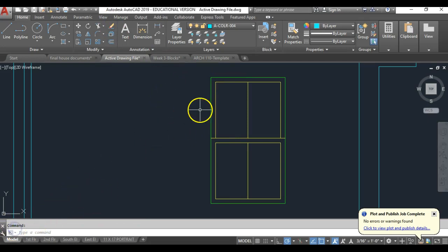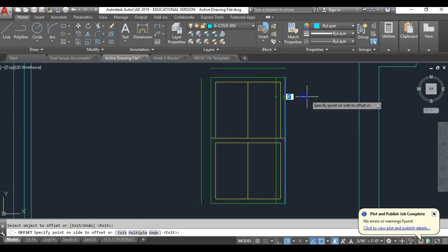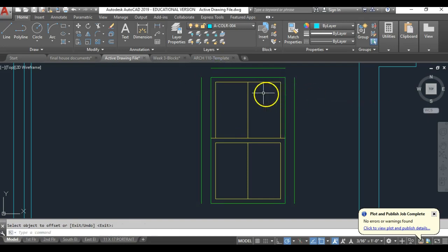And the internal trim of this window is going to be similar but slightly different than the outside. So it's going to be 4 inches as a base. So I'm going to go offset 4, enter, and do 3 sides of this only for now. We'll see, because we have the sill on the inside that we have to draw on the bottom. That's why I'm only doing these 3 sides at first. And I'm going to fillet it. You can do F enter for a shortcut there